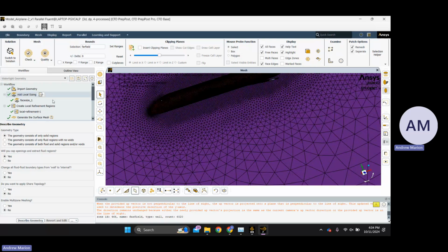And there's a lot more. You can do it for edges, and a lot of other stuff. The types of mesh controls you can use are a deep rabbit hole of whatever is applicable to your situation. The most common types for aircraft are the region and the face sizing, and sometimes inflation layers.